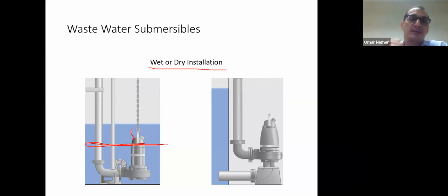But if there is a must to empty this pit completely, for example, if I need to empty it to this level, I need a long time to remove all this liquid from here to here, then you need a cooling jacket, even if it's wet installation.